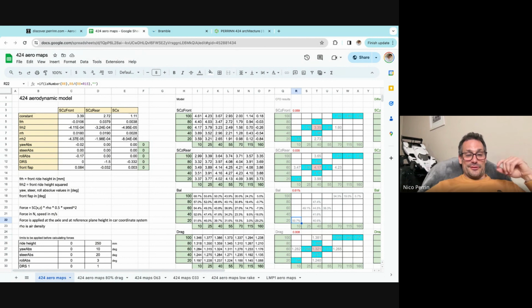So you see there's a lot of details and work that's gone through developing these systems. It was a combination of spending time with our test drivers, going around the Nürburgring, complaining about the balance in high speed versus low speeds, and then working the DRS activation and how to best use it just to optimize lap time. And we needed to have this aero map model so we could keep upgrading the car and then let our test drivers drive the evolution of the aero maps.